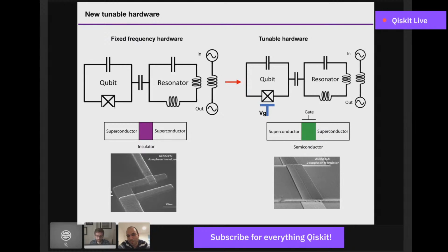For this, it's just younger. So we haven't done that much. We haven't optimized the gate stack. We haven't changed the substrates and all that. But I agree, with the SQUID you can do 10 nanoseconds easily now, maybe even faster. Because you can have superconducting coax lines going from your 15 millikelvin up to 4K, where you can dump a larger thermal load and things like that. Exactly.